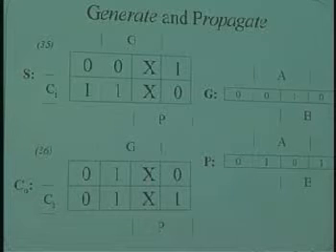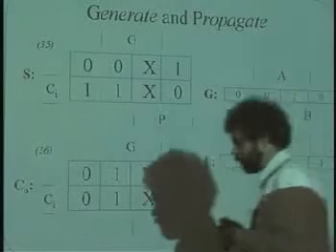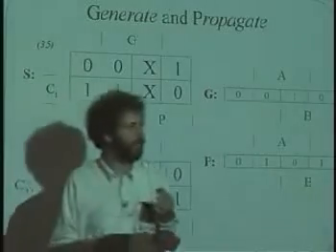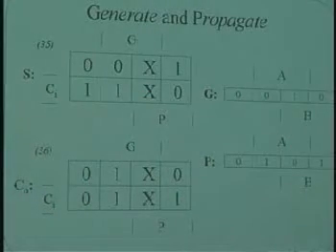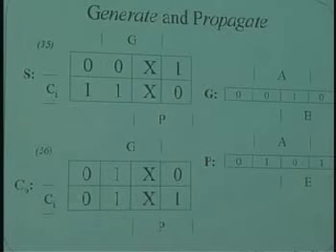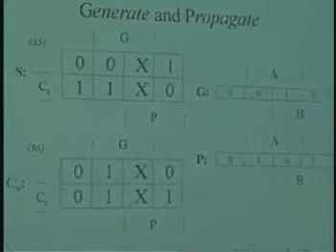And in general, what we're going to do is shift the problem from being one of generating the sum and the carry out to being one of first deciding how to treat the carry. There's really two cases that we need to think about here. One is if I'm adding together numbers and I have one particular bit, if the carry were to come by, would I want to continue to propagate it further on in the chain?